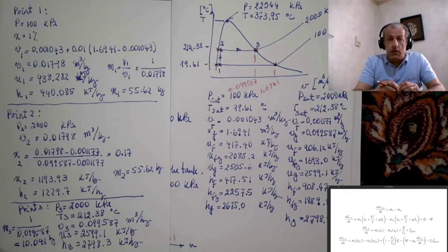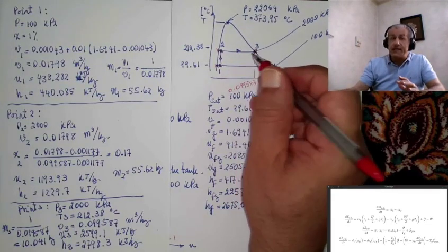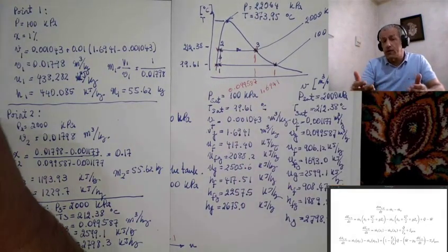The second point is they tell us that there is a volume and there is a valve, and that lets the steam go out at constant pressure. Of course, when steam goes out at constant pressure, pressure remains constant. But there's another value to this statement. Another deduction from this statement is that properties at point 3, that means the exit properties, are all saturated vapor.